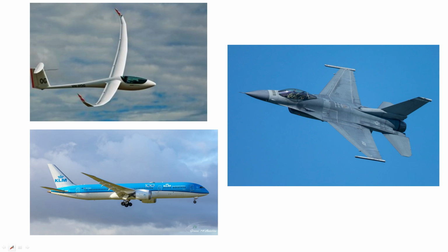One more type is there, the polyhedral type. I forgot to mention it early. This is a polyhedral type wing, a high wing with a polyhedral. That means if I cut this wing at certain extents, the inclination increases gradually. So if I observe from the front view, it's something like this. At each and every interval, it has some inclination.